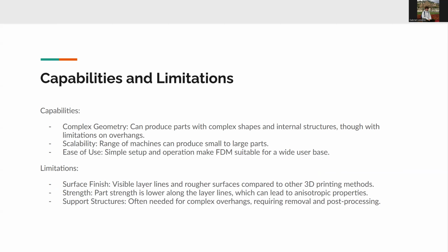And a couple capabilities and limitations. It can create complex geometry, and it is very scalable, and it's extremely easy to use, with very simple setup and operation. It's very suitable for a wider user base. And a couple limitations for this: the surface finish can be poor at times depending on your parameters. Some visible layer lines and rougher surfaces can be seen. Part strength can be lower along layer lines, and often support structures are required for overhangs. That is all.